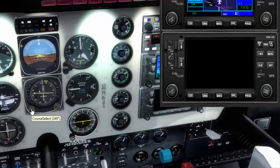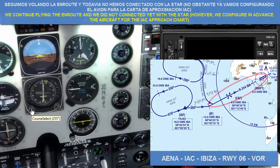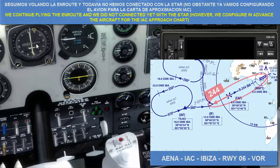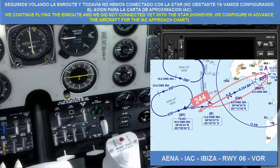Okay, so remember that wheel is the omnidirectional bearing selector and allows us to follow radials. And take a look again at the instrument approach chart. If you look at it, you see radial 244, and you have the VOR identification, Bravo Alpha. But remember, the radial 244 is departing.